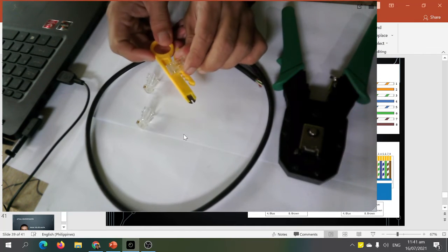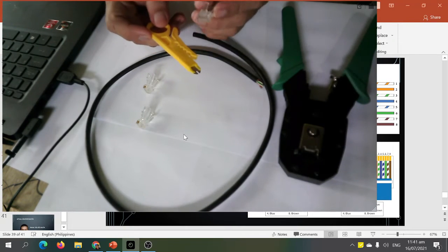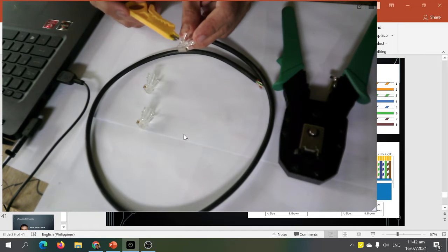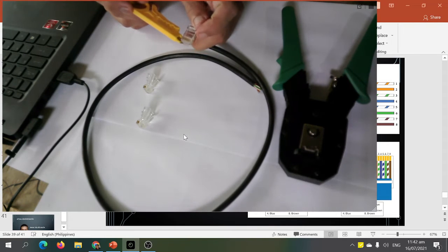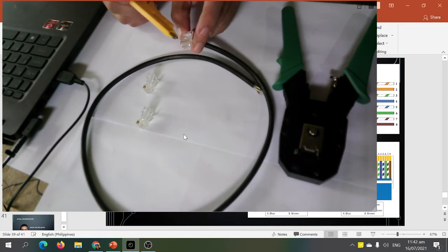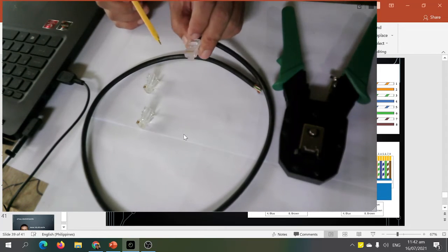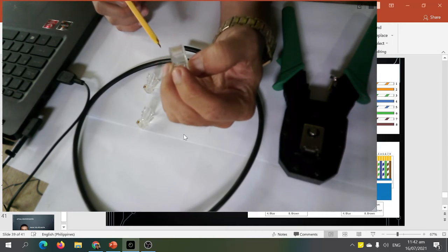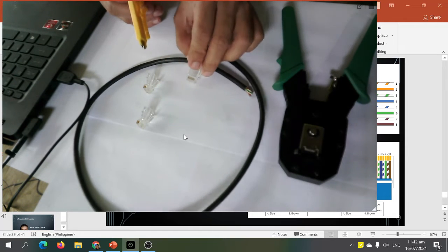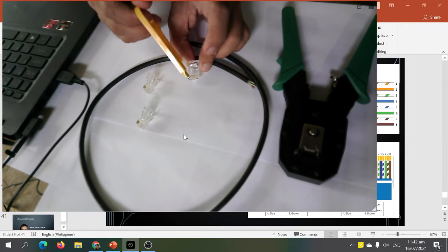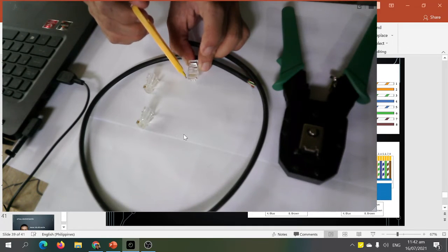So that it is clear, by the way, this is the lock of your network connector. Then if we flip it, pin 1 is on this side. Okay? So pin 1 is this one. This one is pin 1, then 2, 3, 4, 5, 6, 7, 8.